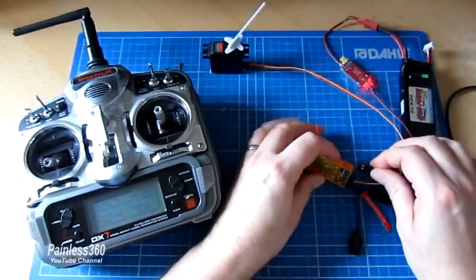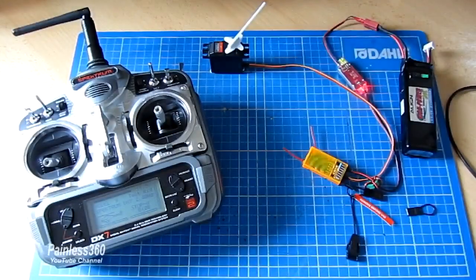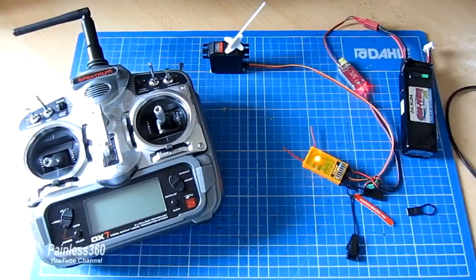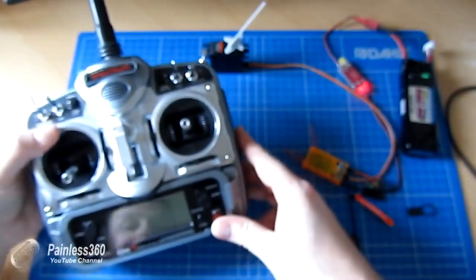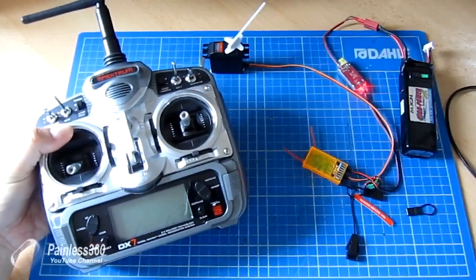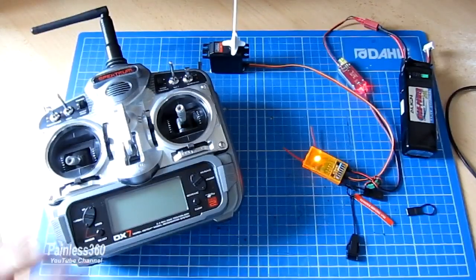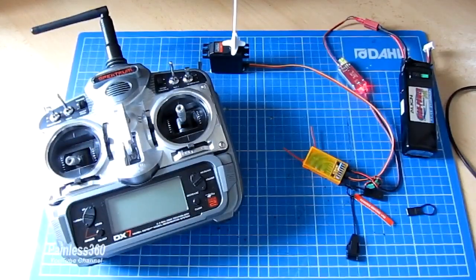And what you'll notice is that the receiver will start flashing like crazy. That means the receiver is just sat there waiting to hear for a connection request from the radio. So let's bind to it. The way it works on this radio is you have to press and hold this button on the back as you power the radio up, and then once that process has started, you let go of the bind button at the back, and the bind is successful. We'll confirm it all works by turning the radio off, and there we are, that all looks good.